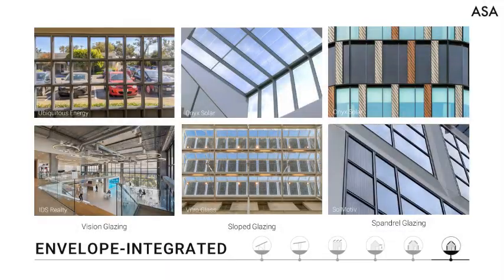Vision glazing applications offer the best opportunity to apply solar technologies to large glass areas. Currently, there are several technologies being developed that are focused on this expansive market opportunity. Some utilize organic PV coatings that are nearly invisible, such as the images courtesy of Ubiquitous Energy. Others place the solar cells within the perimeter of the window and direct light via film within the outboard laminate. And the most readily available option is amorphous silicon products that integrate thin film products into an outboard laminate.